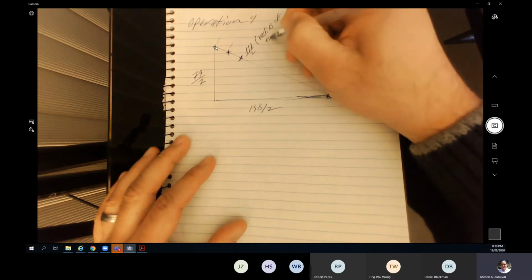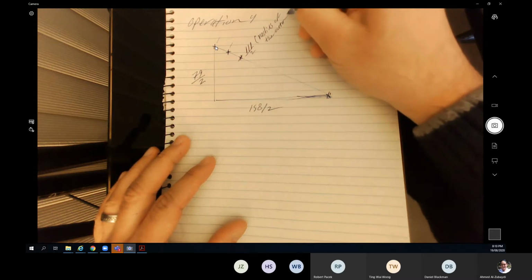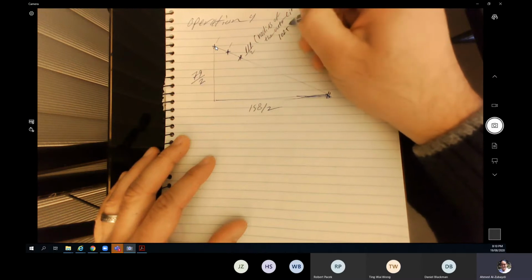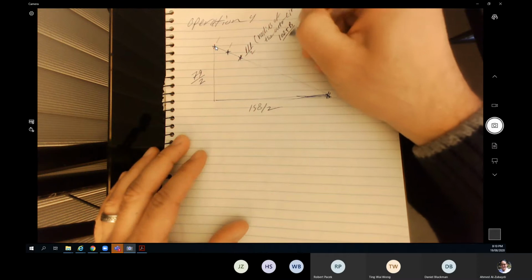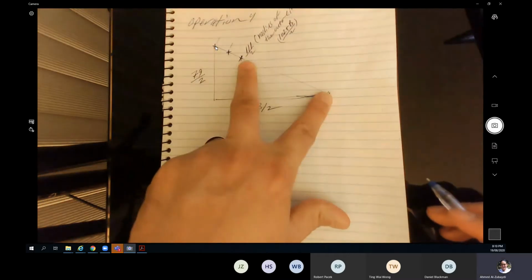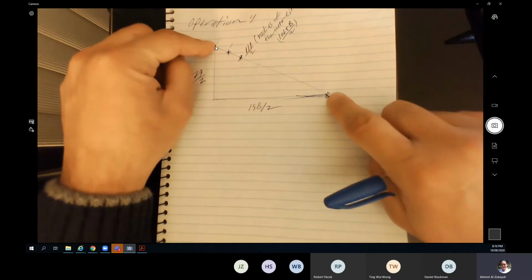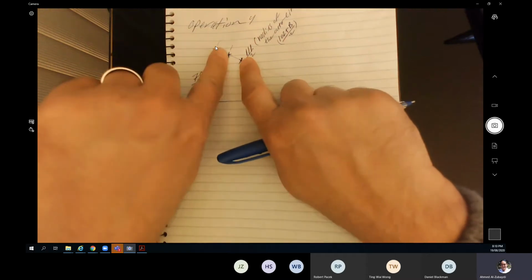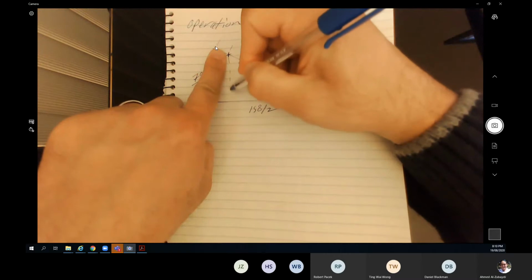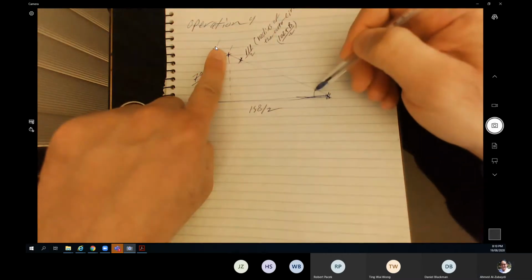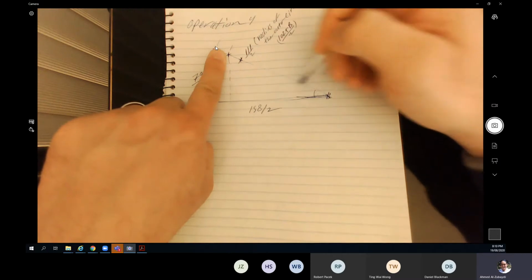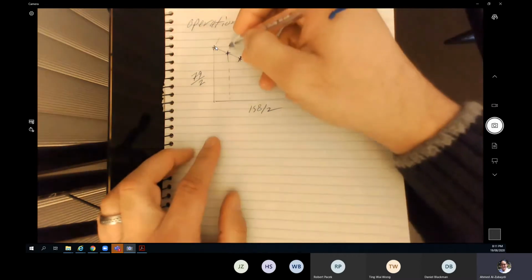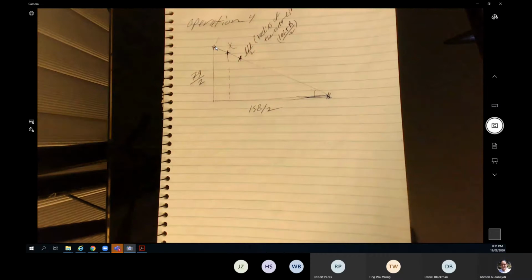of the outer circle, which is 102 plus b, which is 9, divided by 2. So I can find this length. Subtract, we will have this length. Divided by 2, we will have this length. Then I can make another triangle, knowing the angle and knowing this length, multiplied by the sine of this angle, we will find this height. So I find the value of this point, which is going to be the center of this hole.